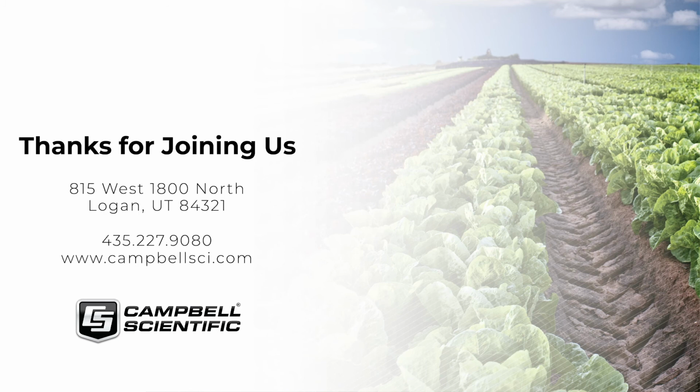So you measure the soil, mix up a batch of soil with a known amount of water, and measure that with the sensor, and then take soil samples of known volume, and then measure the wet and dry weights of those samples of soil, and then repeat that for different levels of water content. And then you can develop that relationship. If it is one of the permittivity sensors, then it's probably best to use the permittivity rather than the volumetric water content. But you could do it with the VWC as well.